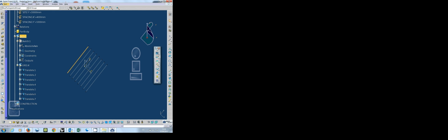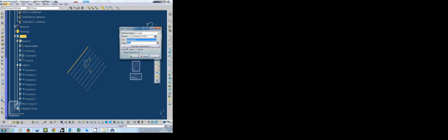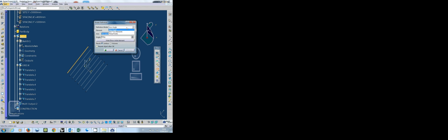Okay, so this is the tool set we need for now. I pick this object, and this time I use rotation, right? Rotate. You can select the method. There are 3 methods to do rotate. So I need the axis. I've got the input element. For the axis, you can pick something in the model if you have, or you can just right click and find a z-axis. It will take the origin point, z-axis, locating the origin point, and rotate it. You can rotate manually, or just say 90 degree.